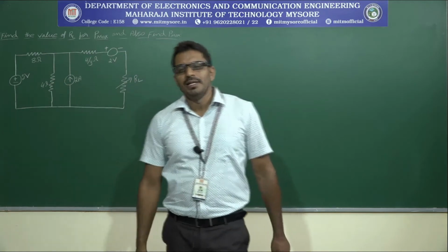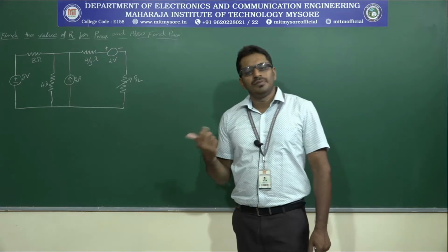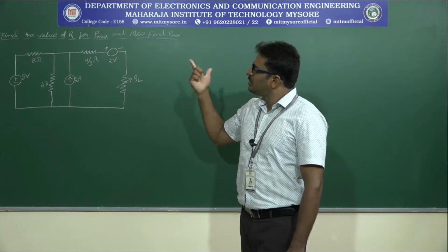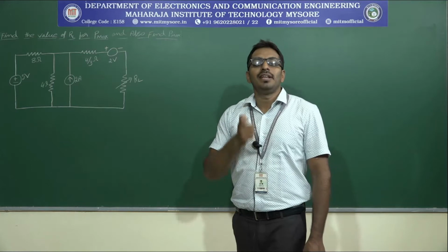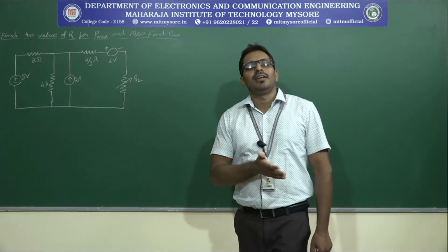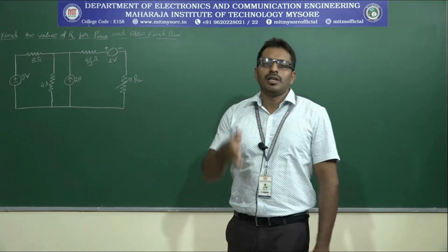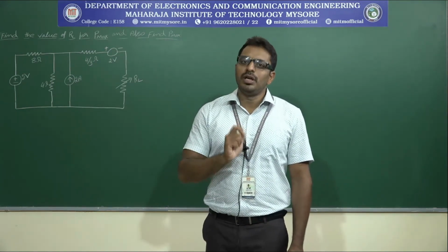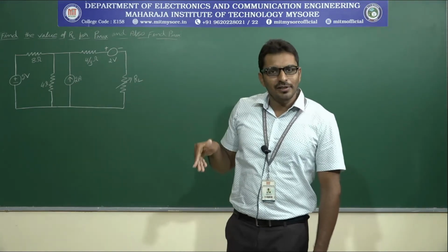Is that clear? We already discussed Thevenin's theorem and Norton's theorem. While solving any problem using the maximum power transfer theorem, first we need to obtain Thevenin's equivalent circuit. We follow Thevenin's theorem to obtain it, because Thevenin's equivalent circuit consists of one source with an internal resistance or impedance, which is finally connected to the load.